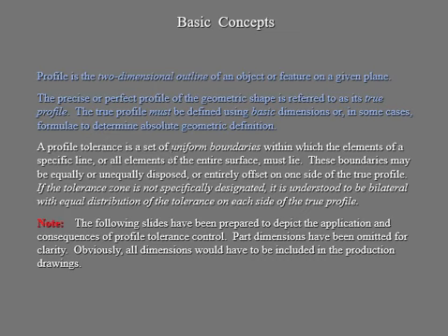So we will jump this and then go into the profile tolerance. Tolerance, again, is a zone, so you have an upper and a lower limit, which is linked to the upper and lower limit of the size of the feature. We are looking only at the outline of the surface, so your profile tolerance is your boundaries, where you can have errors in manufacturing processes.